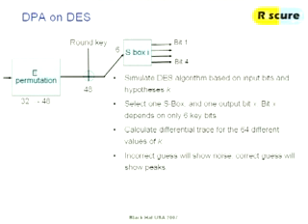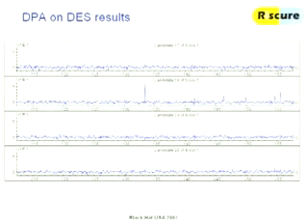So we actually simulate the DES all the way up to the point of the output of the S-box. And we calculate the output of the S-box for all the 64 keys that we can have for that subset, combined with our random input. And if we have sufficient random input going in there, then this will eventually give you a correlation that's very strong for the correct key and 0 for all the other keys, which looks something like this.